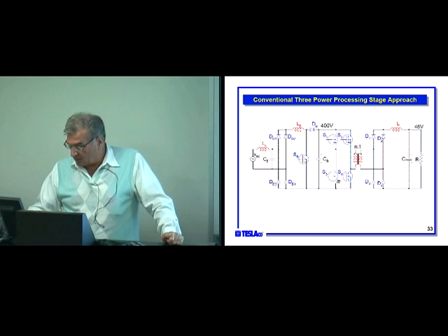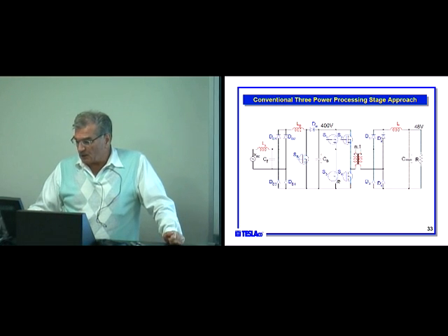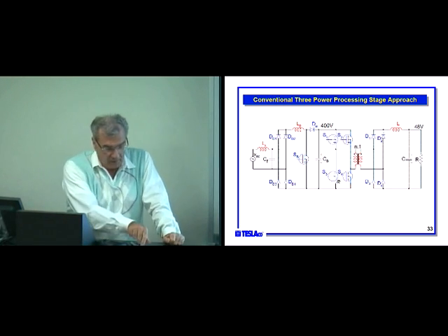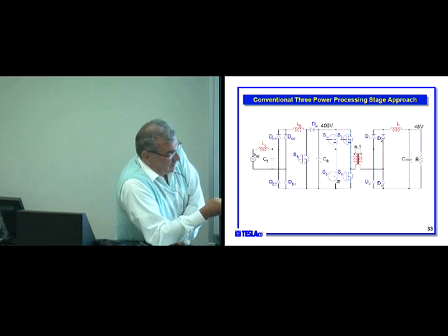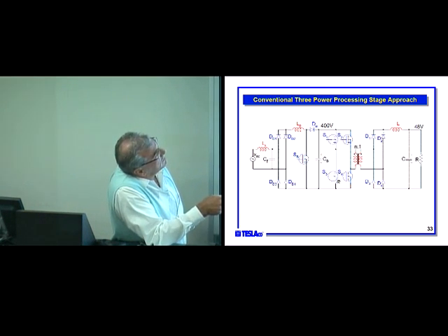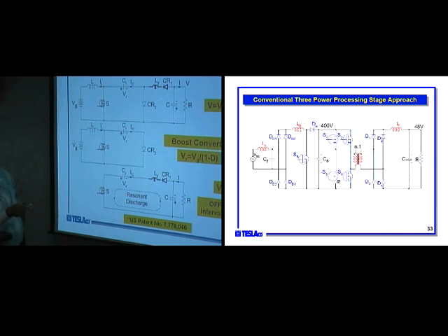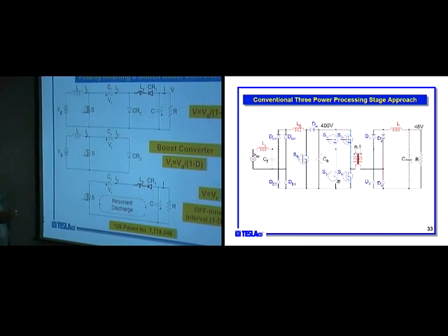So what we did is, I said, okay, how about if I have, and you can see here, I started with the original Ćuk converter with this inductor. And I did something which is kind of a, let's say, no-no. You put a switch in series with the inductor. Now, in actual circuit theory, you can't put a switch in series with an inductor.